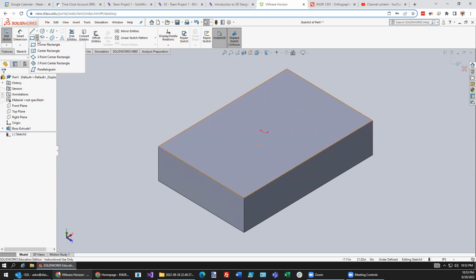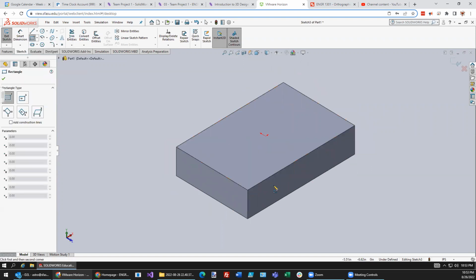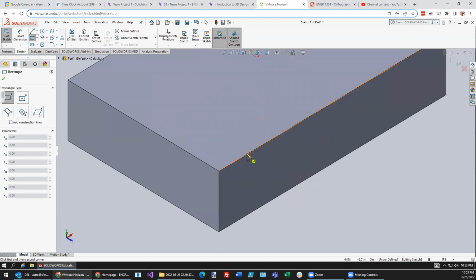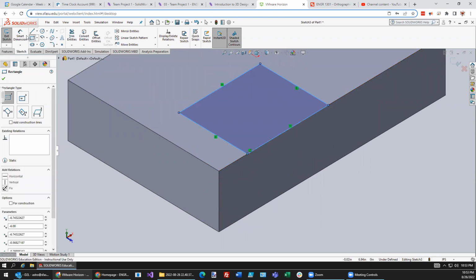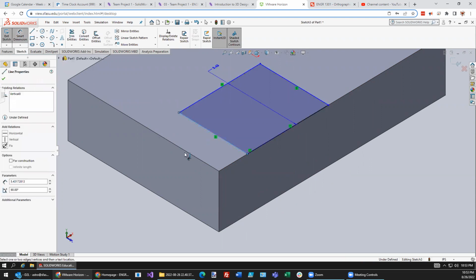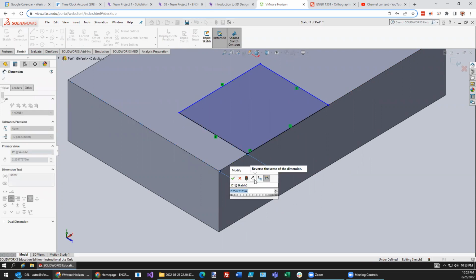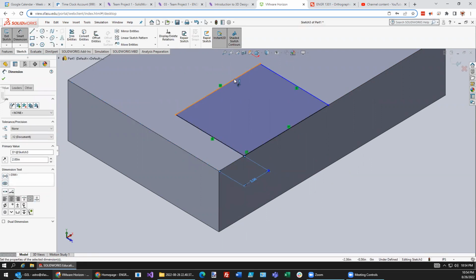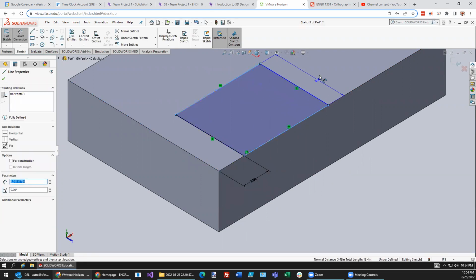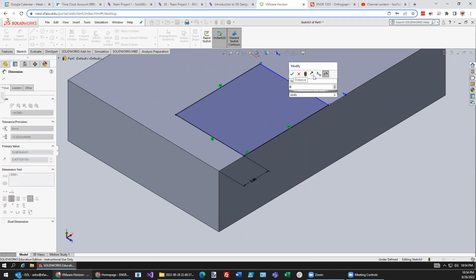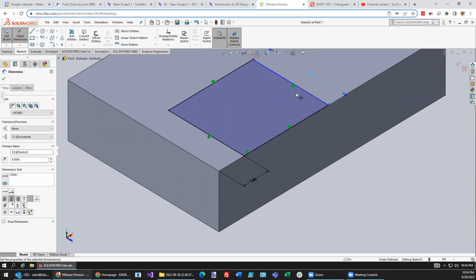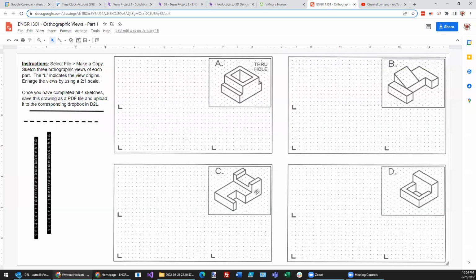And now let's go back and do the corner rectangle. And I'm going to use my scroll wheel to make sure that I'm right there on the edge before I make that cut. So Control Z is your friend when you end up making an error, just like I did. Then going over here, we said this one's going to be 2 inches. We said this one's going to be cut right in the middle, so it's going to be 6 inches this way.